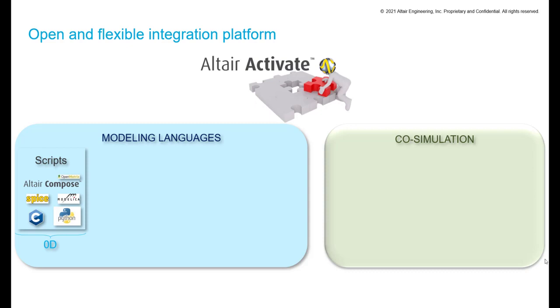So you can design subsystems in Activate using a mathematical approach, using just scripting, and it embraces many languages for scripting: C code, SPICE for electronic component modeling, Modelica for physical components, Python, and our own Open Matrix Language, OML, which is a matrix-based language for mathematical scripting.